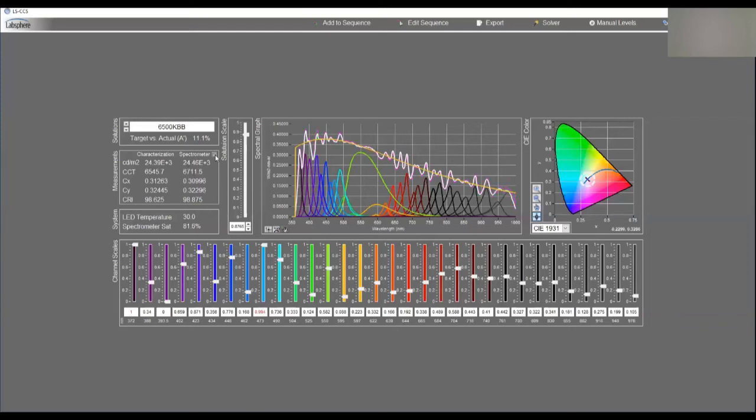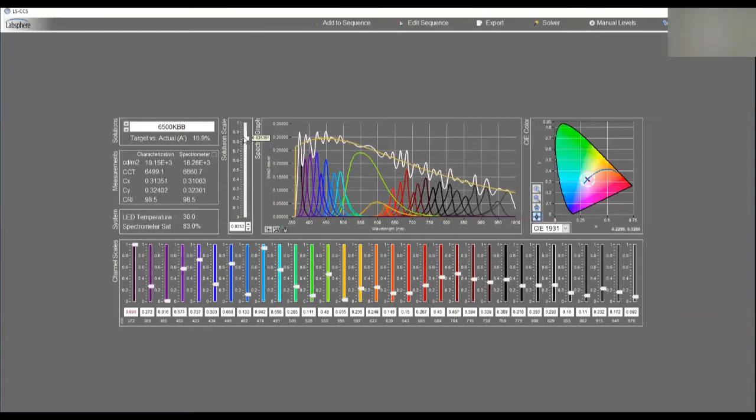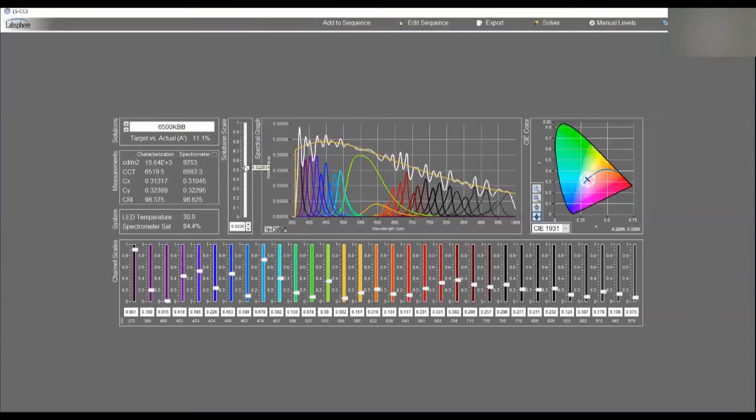The spectroradiometer can be turned on and off. And as always with these systems, they're characterized and calibrated over the full dynamic range of the system. What I want to show you today is how do you combine 2 spectrum? For example, what a surface might look like, a reflective surface, and the rendering of that surface when illuminated with a different light source or spectrum, and then have our FT2300 be able to reproduce that combination of the reflectance and illumination source.